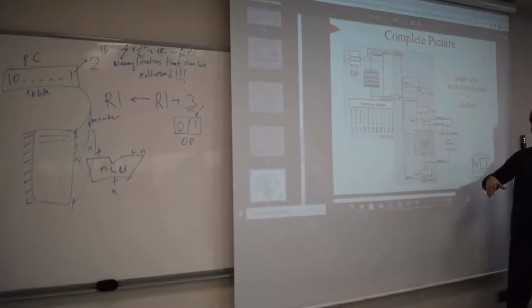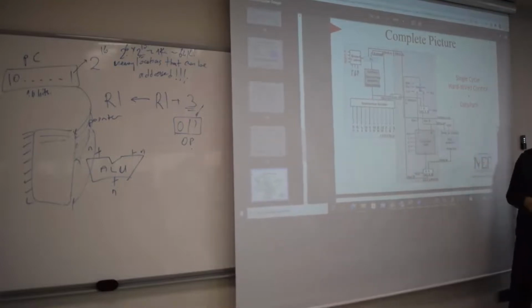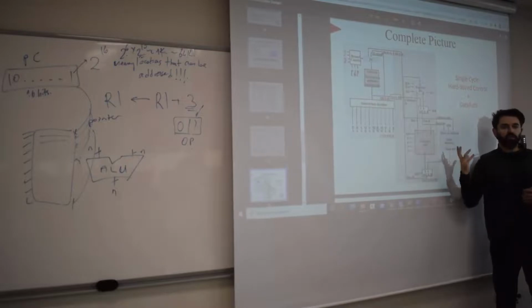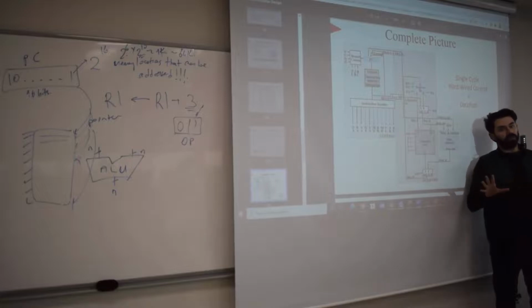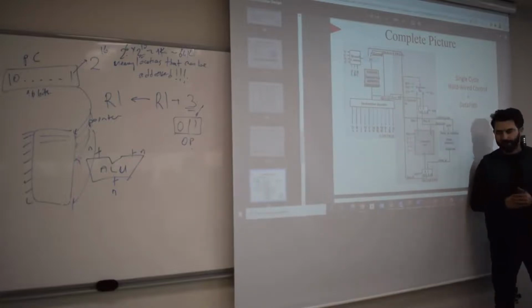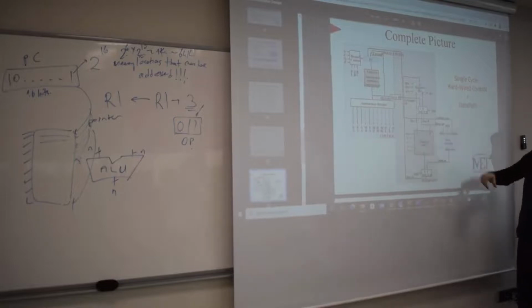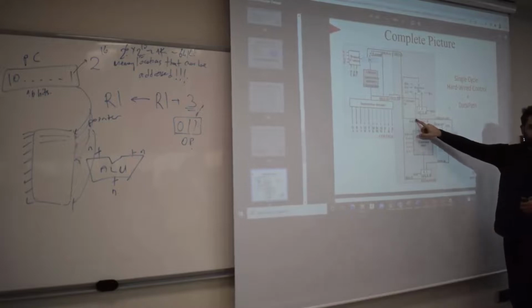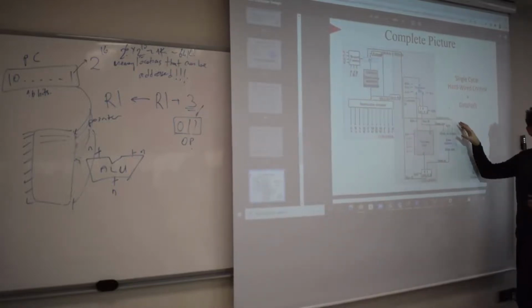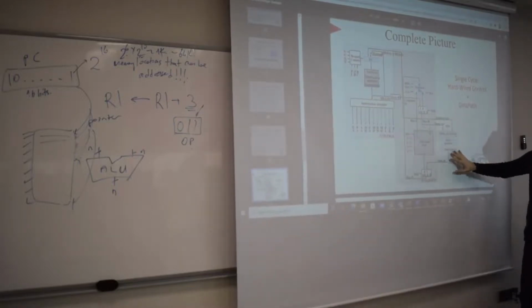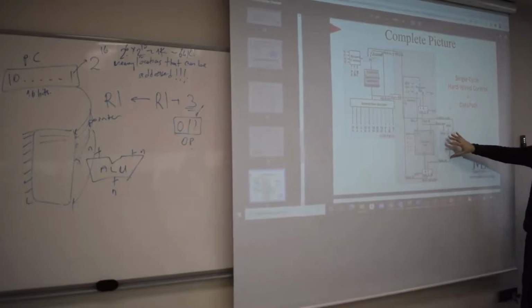If it is 0, you read. If it is 1, you write, okay? Whenever you have a sequential memory element in your design, please put a control bit to write and read. Otherwise, your data may be corrupted. It's at risk. So in order to bring that risk to 0, put a control bit here. Now, you see those wires were just going out and not connected. Now it's connected and part of the architecture here.